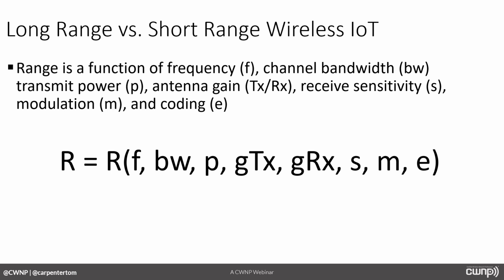Okay. So you know about these things if you've studied Wi-Fi, right? You already understand that you have longer range with 2.4 gigahertz than with 5 gigahertz due to the aperture of the antennas, due to the design limitations of 5 gigahertz antennas, and that even though the signal has propagated there, we can't pick it up as easily with the antennas that we manufacture.